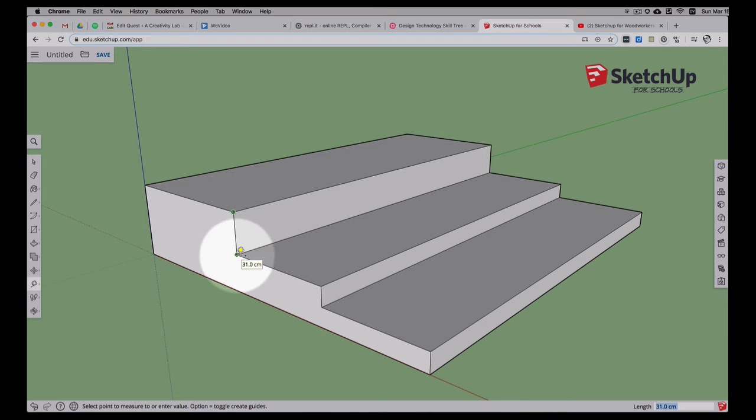If we click here and go down, that's 31 centimeters. I can even click on diagonals and get the measure of a diagonal here. About 86.3 centimeters. Notice that tilde there. That's because we had our measurement system locked to 1/10 of a centimeter as the smallest amount. So it's not quite 86.3 centimeters, but it's not 86.2 either. It's somewhere in between. By setting the measurement scale to a finer granularity, I can find out exactly what that is, but in this case, we don't really need to.